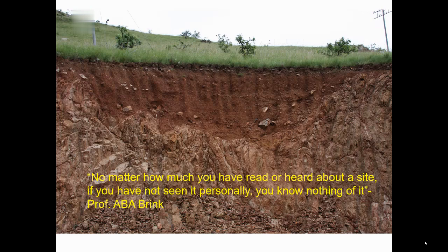Professor Tony Brink once said to me, no matter how much you've read or heard about a site, if you have not seen it personally, you know nothing of it. That's quite a strong statement, but I'm giving you this advice because often your clients will try to prevent you, or not pay for, a reconnaissance visit. A reconnaissance visit can be as little as 15 minutes on site.